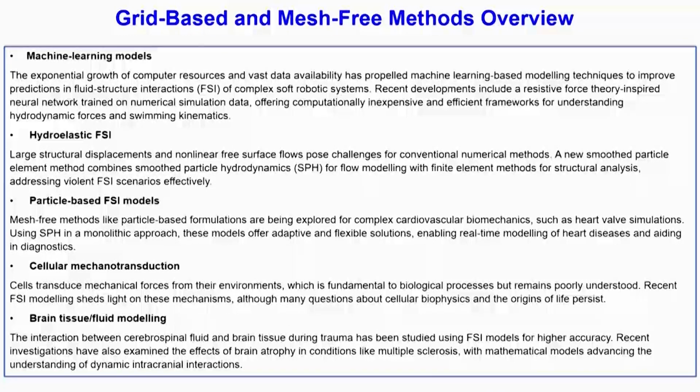In structural mechanics there can be many violent scenarios. Violent means large displacement. So, for example, you have a bridge and some wind or some load which is coming on the bridge, which is oscillatory in nature. So, you have a forced vibration. If the natural frequency of the bridge is the same as that forced vibration frequency, you get resonance, and then it will theoretically vibrate with infinite amplitude. So, you have large amplitude motion possible.